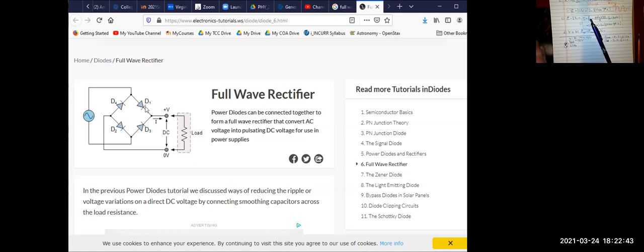It's called a diode. And a diode basically has limits. It's got a certain amount of power it can deal with, and if you have too much power, it's going to burn it up. But as long as you stay below that power, then it acts like basically a one-way valve. So it only allows positive current, positive charges, to flow this direction. It doesn't allow positive charges to flow this direction, as long as you keep it inside of its range. So when we picture conventional current, we picture the positive side having positive particles coming out this way, like protons or something, and the protons would actually be allowed to go this way. They're not allowed to go that way because that's a stop. So it, lo and behold, also can't go this way. So it goes right here to what you call the positive side.